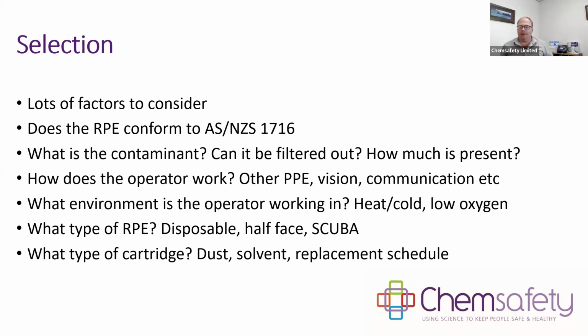There was a job I did a few years ago where we had to work this out. They used a solvent, they decanted it in one room. The decanting process from the drum to the vessel that they used it in took about 10 minutes. This was a highly volatile solvent, so we're talking about those AX filter cartridges you mentioned earlier. They cost a couple $100 a pop. They were having to use a brand new one every day for the 10-minute period that they used it. So once per day, they'd decant this solvent for what they needed. And each day they had to use a brand new set of filters because that was how much capacity this filter had to hold that level of solvent. Often they can last a bit longer.